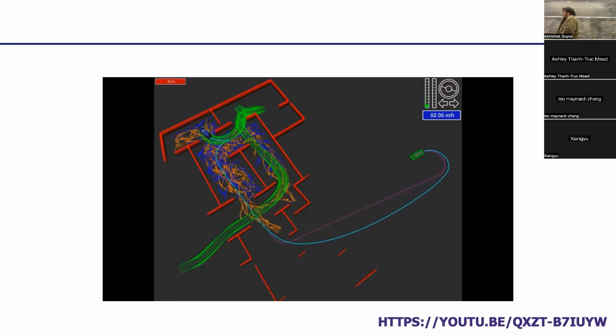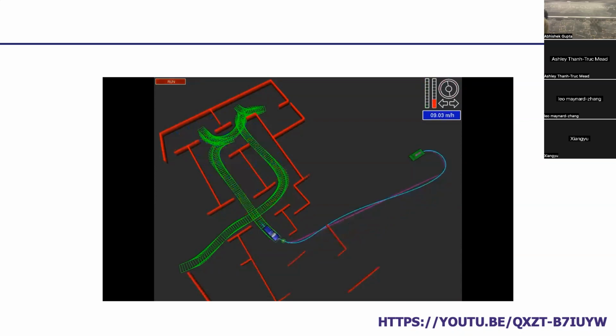And so in these self-driving scenarios, when the map is not fully known, and right now downstairs you map out the whole environment, but often in deployment you don't have that. And so we want methods that are efficient in replanning and able to do it in real time because your cars are moving fast, right? And so those are some of the challenges that we would encounter in motion planning: things that are high dimensional, things that have lots of physical constraints, doing things in real time, doing things very gently, right?